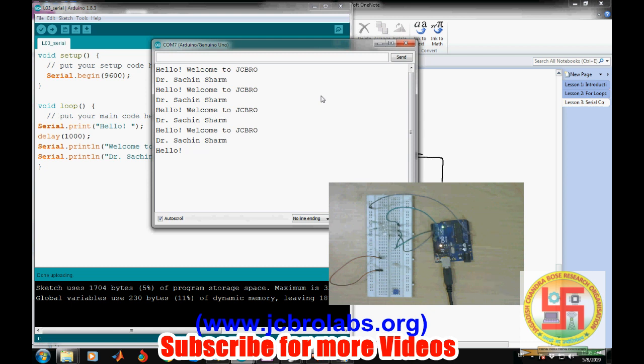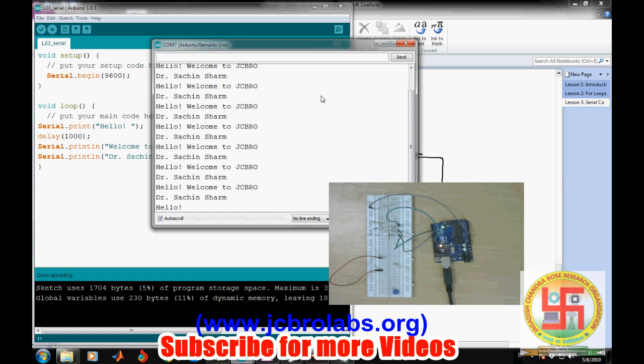Okay, so this is not only good for testing, like sending some data. It is also good to let the user understand which state your microcontroller is currently in. Suppose you are writing a big program, and you want to put some checkpoints in between, so you can use this serial monitor to understand what is actually happening. So let's test what exactly I am trying to say.